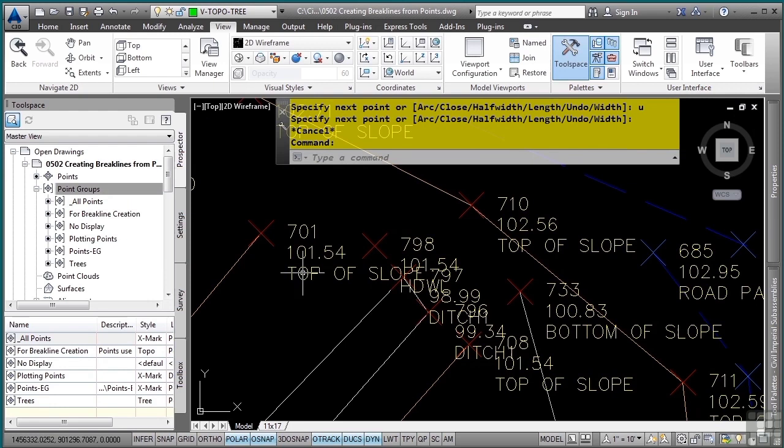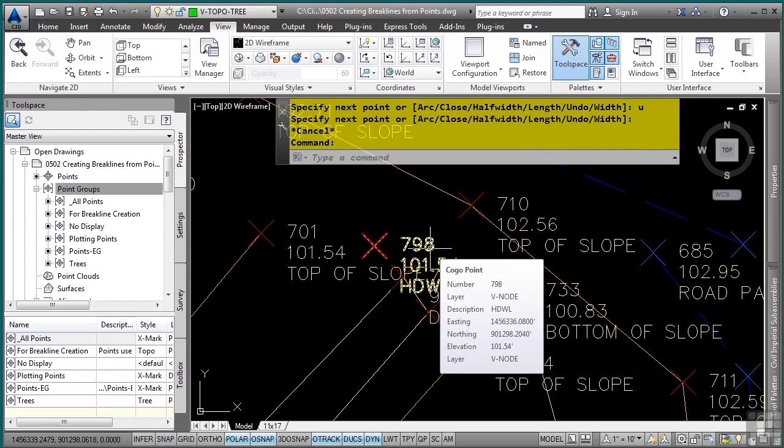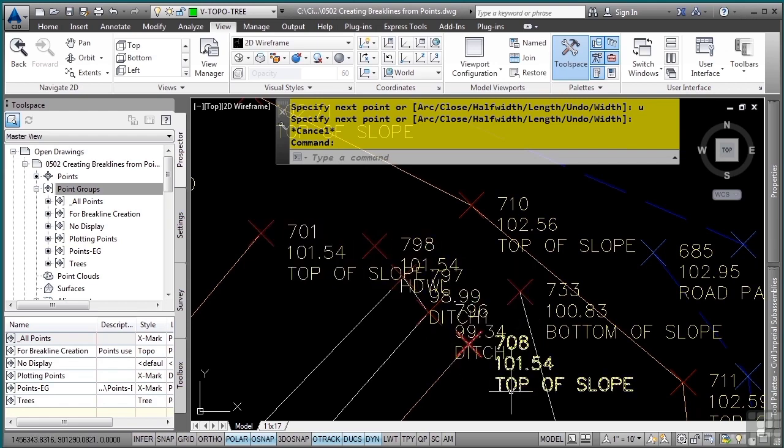Let's say the surveyors forgot to locate these points with the correct description. And in this instance, we actually have a head wall that we want to go in and create here that we will eventually use the head wall type break line. So you'll notice I have one point with head wall, and notice how the elevations are the same here. So I need these 3 points as the head wall. If you're going to do a head wall, you must have a 3D polyline. That way it can grab the actual elevations from the head wall object.